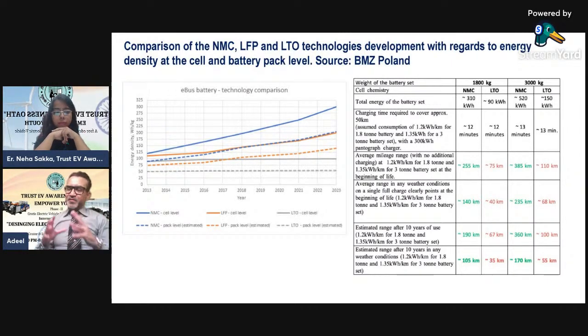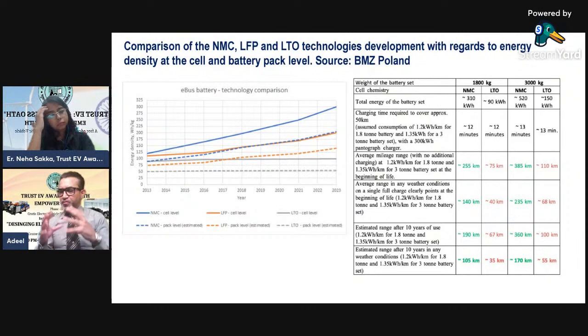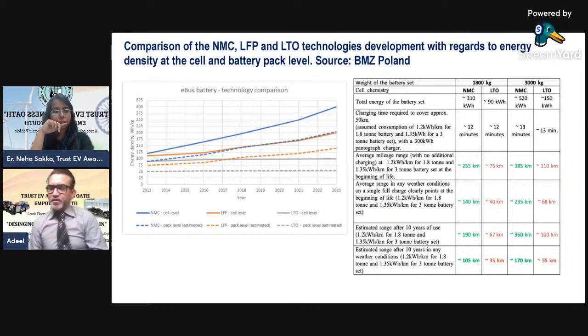So it all depends upon your battery and your car. If I can give you a DC charging station, maybe it can do a quicker job. But then again, your car should be able to take a DC charging port. I have vehicles that cannot take a DC charger because these are small vehicles. I have a 30 kilowatt vehicle which cannot be charged by DC. It can only be charged by AC.